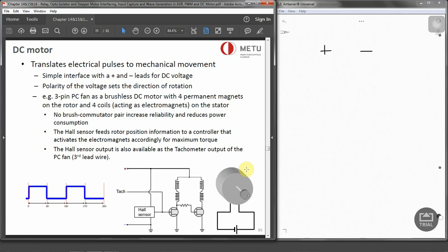As we have already said, as the load increases, the rotation per minute decreases unless the current or the voltage provided to the motor is increased, which in turn increases the torque of the motor. And with a fixed voltage, as the load increases, the current or the power consumption of the DC motor increases. And we have to be careful. If we overload it, the motor will stall. This can damage the motor due to heat generated by the higher current consumption.